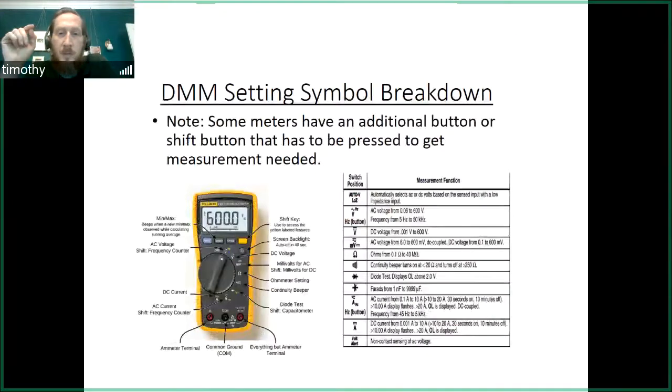Here's the digital multimeter, and for those of you who have not seen it, this thing is great. It has a bunch of functions. It can do voltage in both AC and DC. It can do millivolts, both AC and DC. It can test ohms. It has this continuity beeper, which does this: when you, for instance, connect leads together and close the circuit, it will beep.